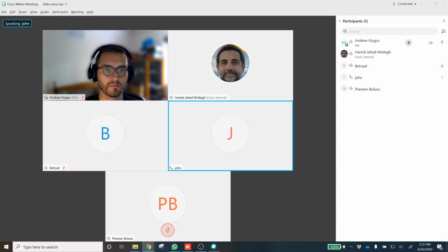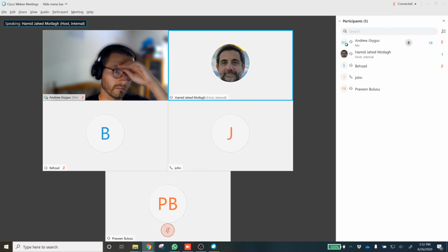Sure. Now, have you done any residual stress measurement after case hardening? No. So one of the things that happens for sure is that you will be inducing some residual stresses, because this case hardening is a surface type of treatment, and therefore the properties at the core are a bit different from the properties at the surface.